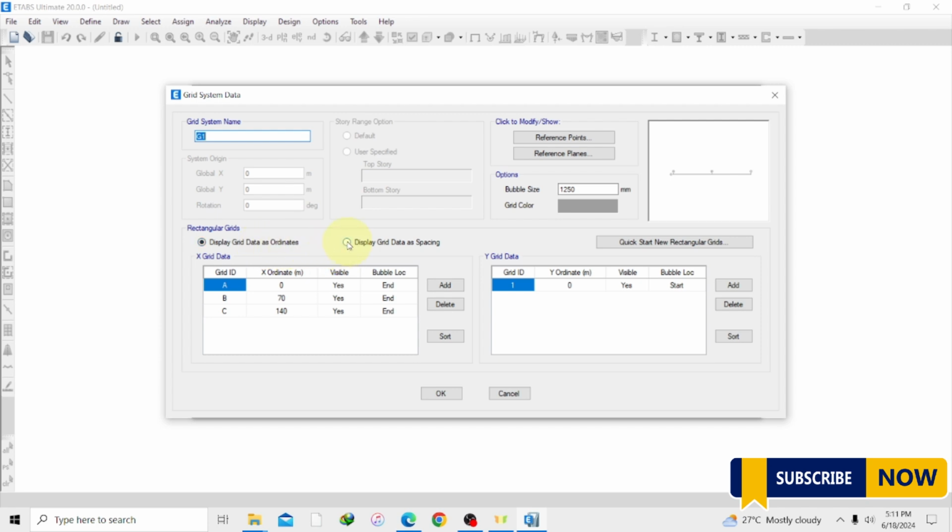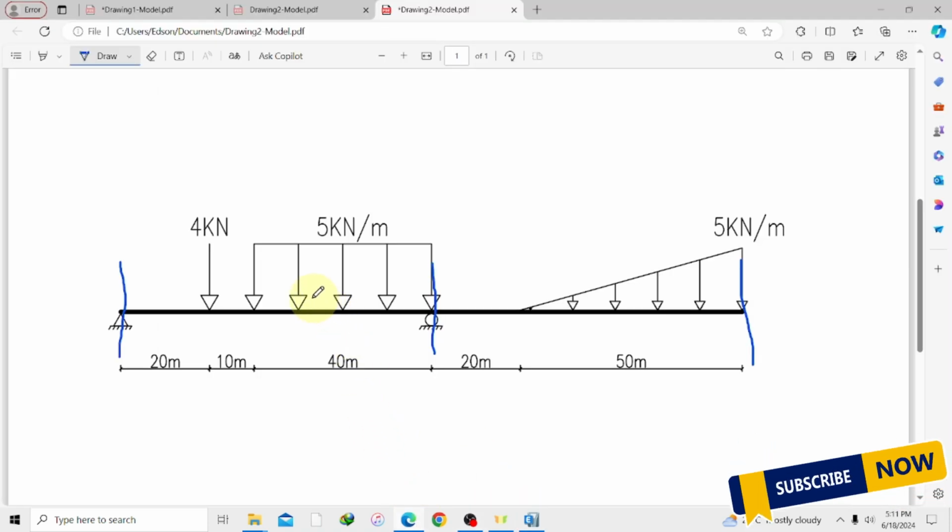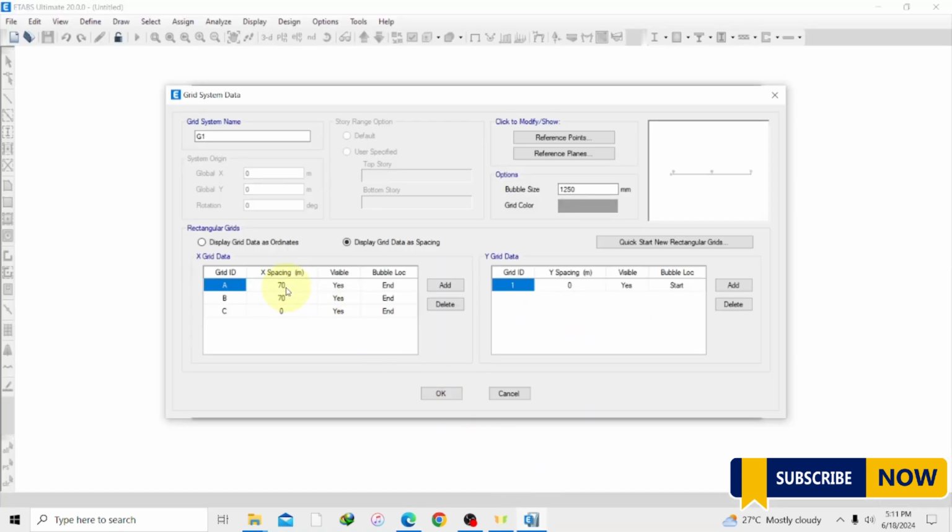So this option displays the data as spacing. When in this option, it displays as a spacing between this grid line and this grid line. So we have 70 meters at this. We have a 70 meter span here, and we also have another 70 meters. So our spacing is 70. So in the case this place was supposed to be 60 and this place was 70, all you have to do is input 60 here and also 70 there.